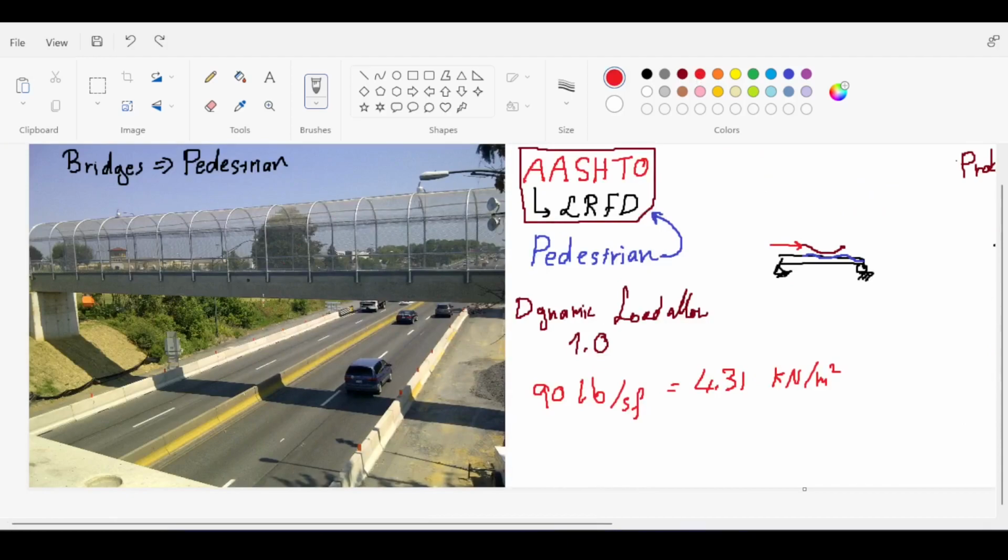The other thing that you need to take into account is something extra that we use for pedestrian bridges. It's called the collision protection for pedestrian bridges. It's a little bit more dangerous for pedestrian bridges when compared to a highway bridge. If this is a highway bridge with cars on it, then you have your own clearances and max heights that you impose. You see those little signs that say 5 meters maximum or something.